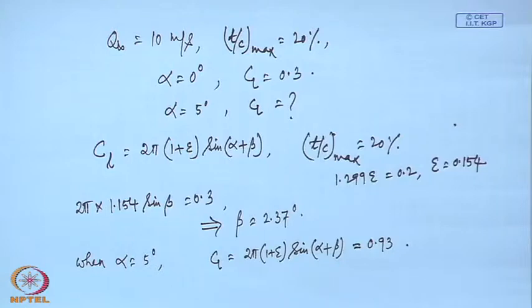Next, you have to find the velocity at the nose of the airfoil. So, once again same procedure, you have to find what is the velocity on the corresponding circle at that point and divide by dz d zeta at that point. So, what is the point at nose?